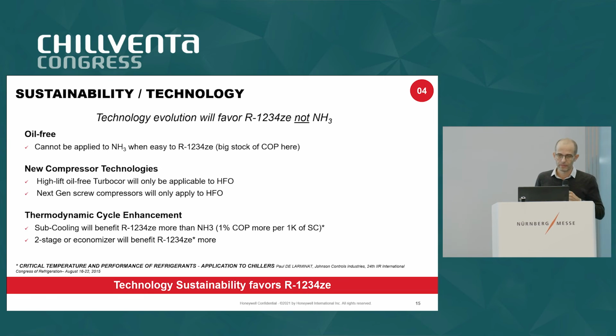They are oil-free and applicable to HFO and mainly Solstice ZE. There are also screw compressors that can be used with HFO and are designed to be efficient with ZE. And if you remember my first slide in this presentation, small enhancements on the thermodynamic cycle can give big steps of enhancement on COP and energy efficiency ratio for this kind of installation.